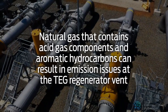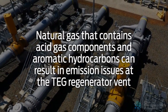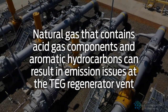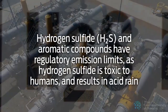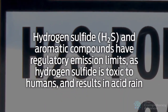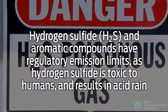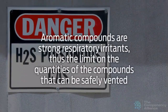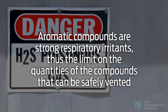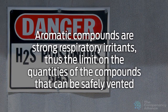Natural gas that contains acid gas components and aromatic hydrocarbons can result in emission issues at the TEG regenerator vent. H2S and aromatic compounds have regulatory emission limits, as hydrogen sulfide is toxic to humans and results in acid rain. Aromatic compounds range from being carcinogenic to strong respiratory irritants, thus the limit on the quantities of the compounds that can be safely vented.